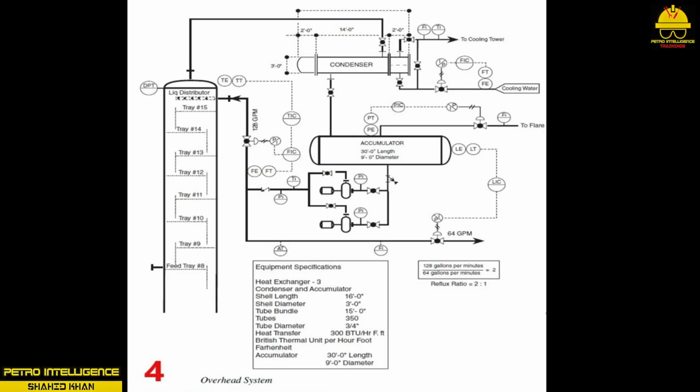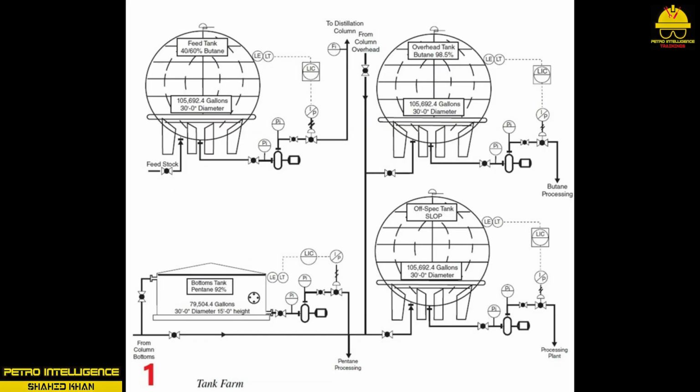15. Set unit pressure at required set point, auto. Monitor pressure during startup. 16. Line up reflux pump to column and off-spec, check suction and discharge. 17. Set overhead accumulator LIC to 50%, auto. Watch level increase during startup. 18. Set reflux FIC to required set point. 19. Line up cooling water and set FIC to required set point. Check suction and discharge lineups.